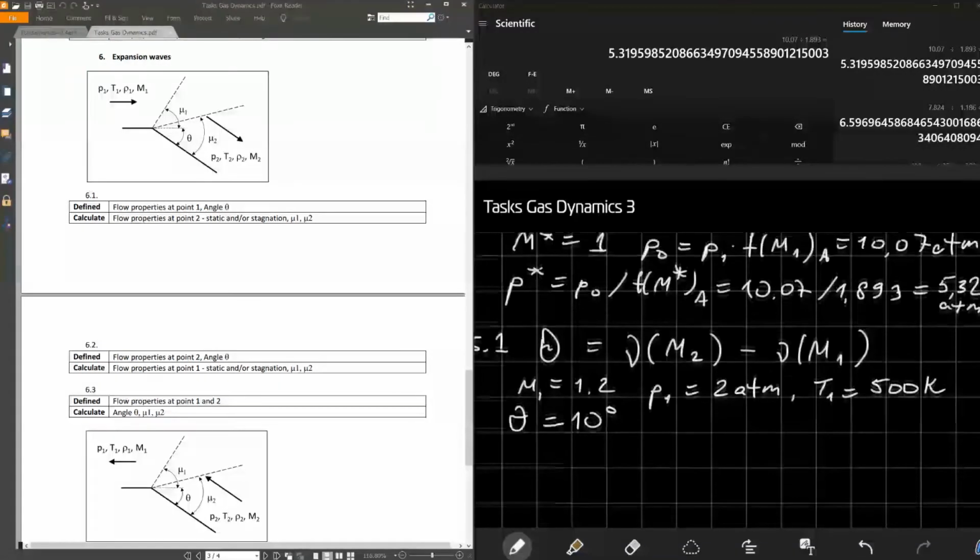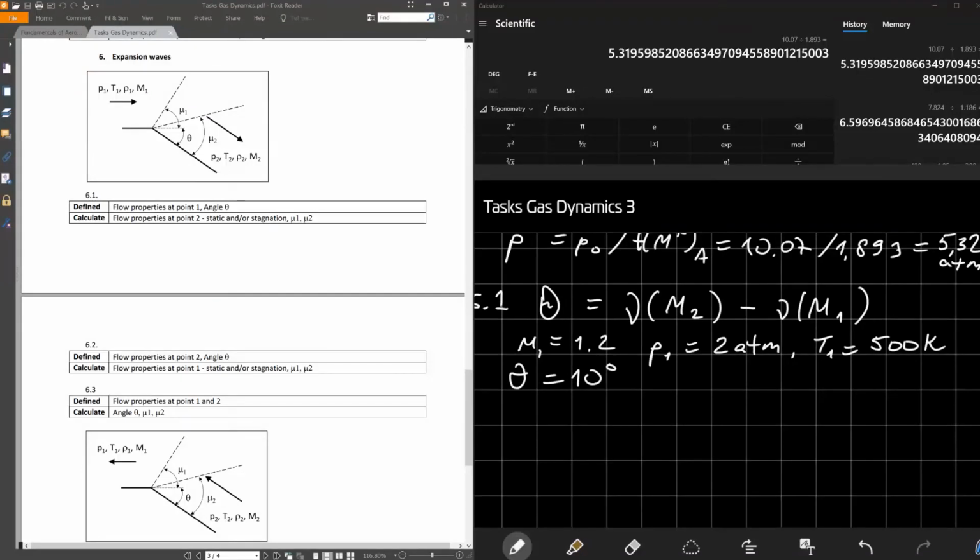Here the model does not say to us whether flow separation will happen or not. We assume that no flow separation happens because the flow is isentropic. Using the Prandtl-Meyer function and appendix C from the book, we are receiving Mach 2.